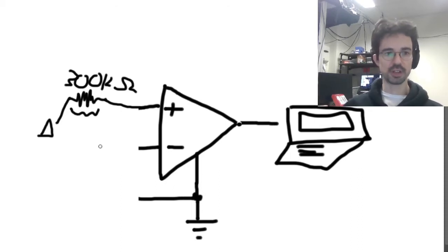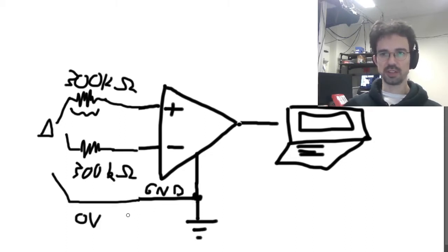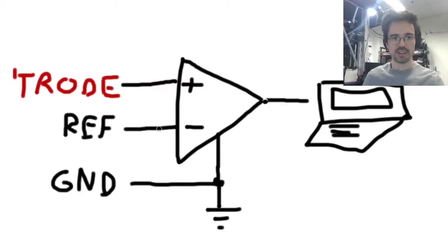The same goes for our reference signal, of course. So if we have some reference electrode that also has a relatively high impedance, then we can still record that signal. Whereas our ground input is able to sink or source as much current as is necessary. So as we'll see, the ground input is really good at one thing, and that is bringing whatever it is connected to close to 0 volts. The reference signal is subtracted from the tetrode signals, in theory, in an exact one-to-one fashion in an instrumentation amplifier, as you've seen in the other videos, with exactly matched input impedance, which gives us very good common mode rejection.